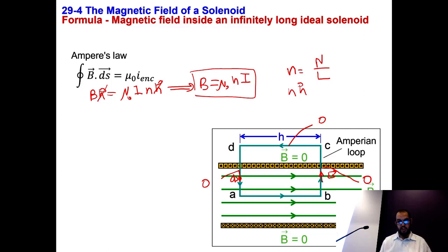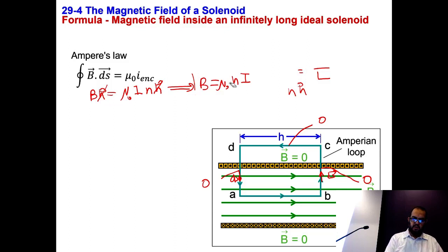Obviously, if you double the current, you double the magnetic field. If you double the number of windings, instead of having, for example, 10 turns per centimeter, let's assume every turn is 1 millimeter, it will give you a certain magnitude. If you double that, for example 20 turns per centimeter, you also double the magnetic field strength. So this is what we will do.